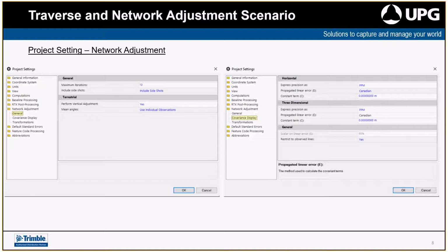I also want to add in that I may have shot to, for instance, an SSM, which is our state survey mark here in New South Wales. I might have shot to it but couldn't traverse to it, so I've just turned it in, and I may have done it from 2 different stations. So I want to add side shots like that in because it's not actually a traverse point.